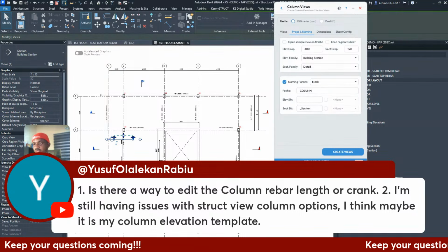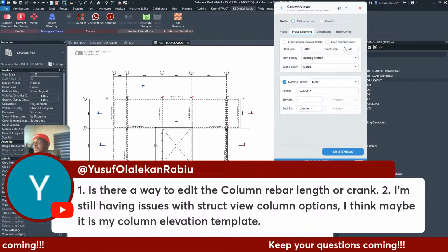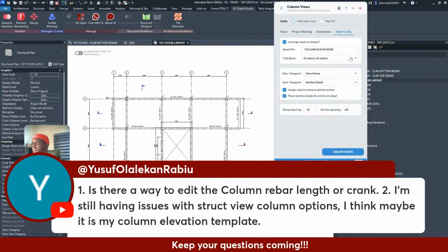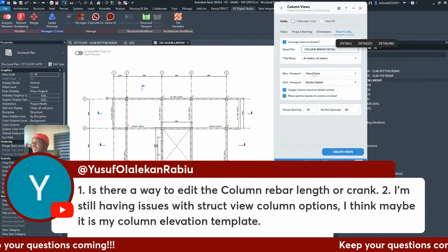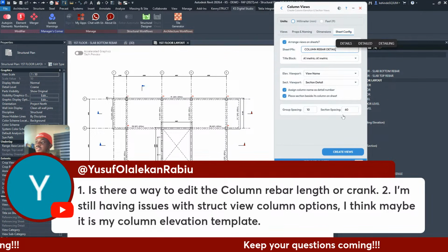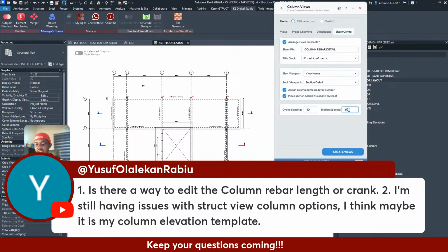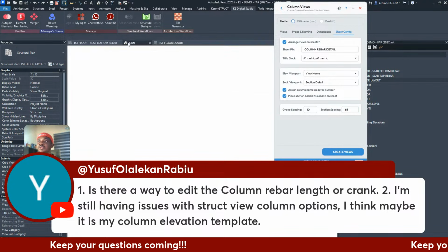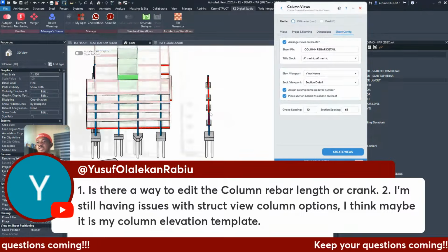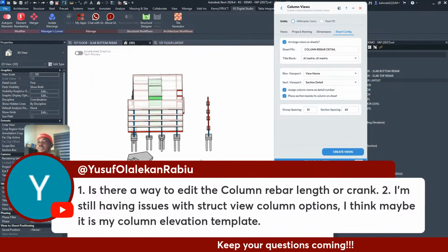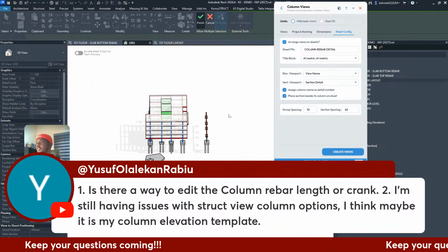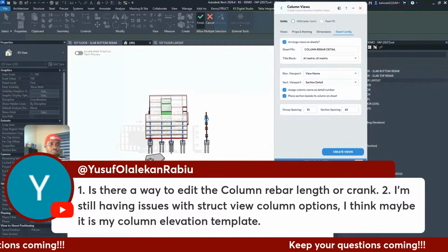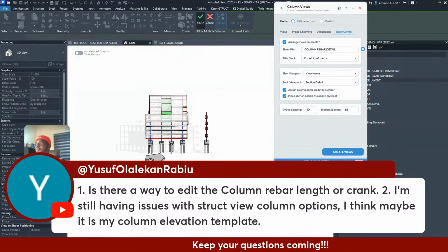So we just need to follow the rules. Very important that we do that. So I come here to system operation and I call this column rebar detail. I tell it to place the section beside this column on the sheet, which is what I want. And the min 65. I come to 3D and 3D view. And I do this previews. Views, like all, then you finish. What will happen? It will create the sheet.